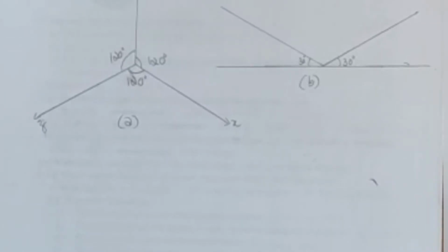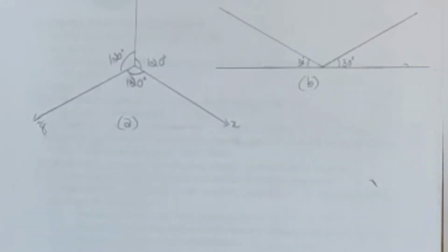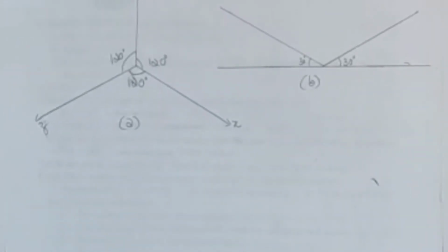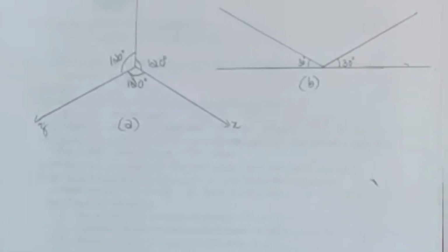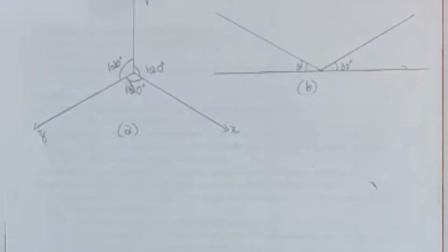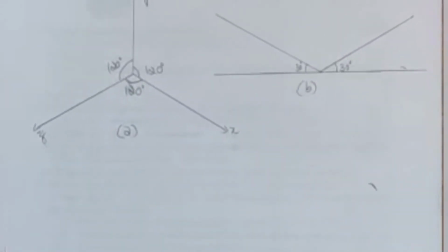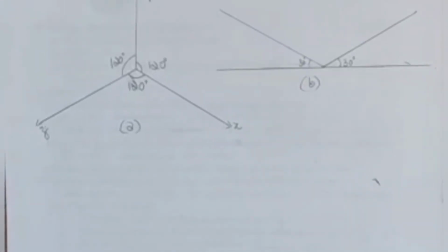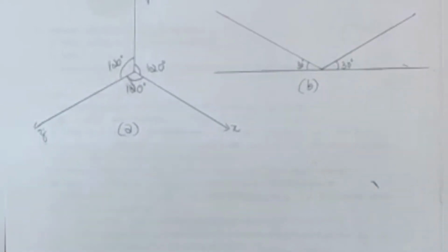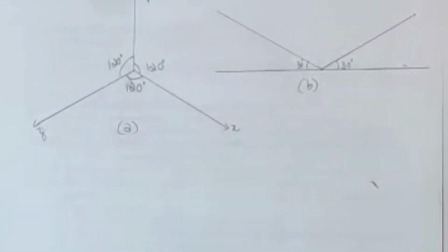This makes it difficult to interpret them, and only a technically trained person can interpret the meaning of these orthographic views. A non-technical person cannot imagine the shape of the object from orthographic projections, whereas isometric projections can be easily understood even by persons without any technical training, because such views show all the three dimensions of an object in the same way. But isometric projections do not show the true shape and size of any principal surface of an object, and they do not show the hidden portions. Isometric projections are easy to imagine, so they are normally used.